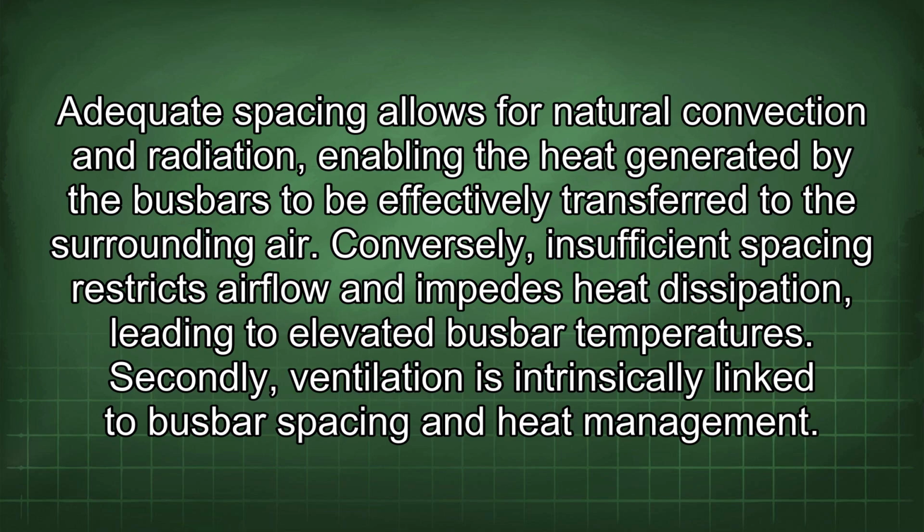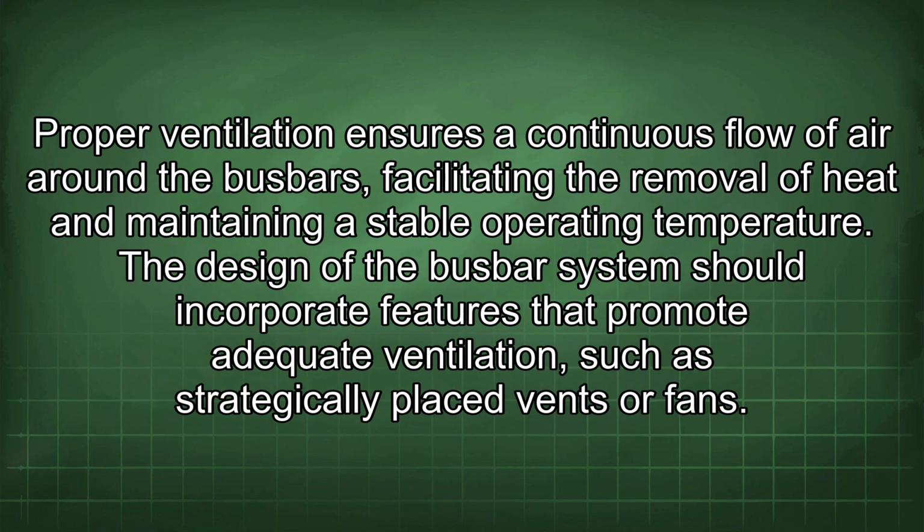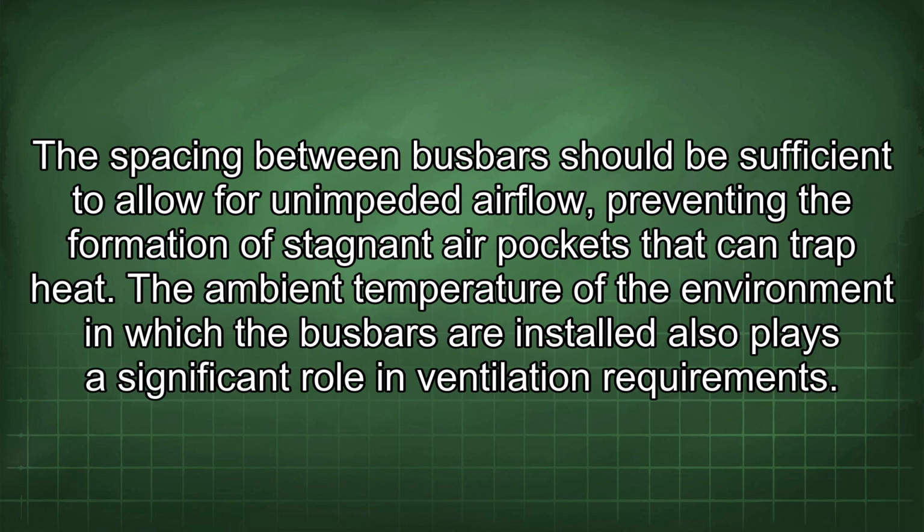Conversely, insufficient spacing restricts airflow and impedes heat dissipation, leading to elevated busbar temperatures. Secondly, ventilation is intrinsically linked to busbar spacing and heat management. Proper ventilation ensures a continuous flow of air around the busbars, facilitating the removal of heat and maintaining a stable operating temperature. The design of the busbar system should incorporate features that promote adequate ventilation, such as strategically placed vents or fans. The spacing between busbars should be sufficient to allow for unimpeded airflow, preventing the formation of stagnant air pockets that can trap heat.